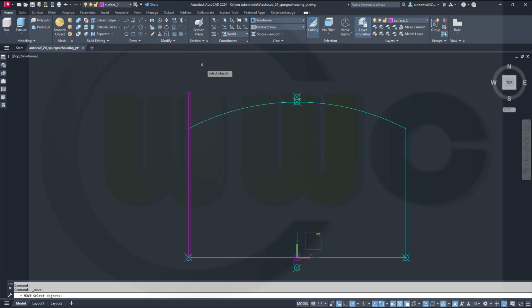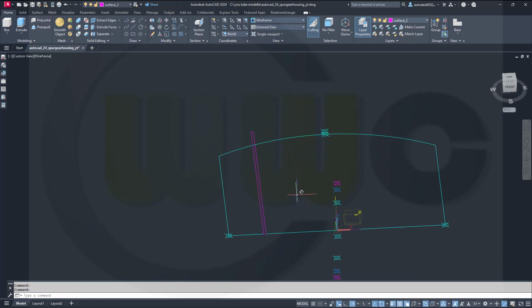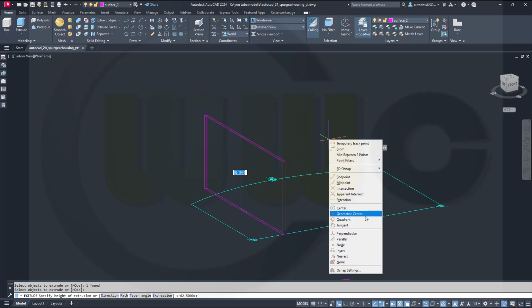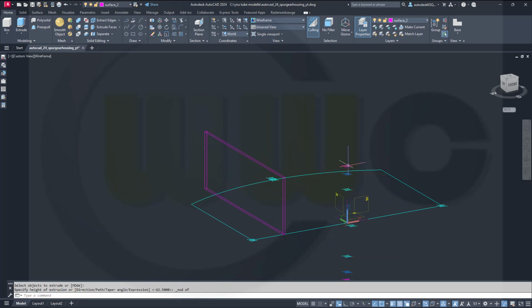So to the move, select that rectangle, right click. The base point could be anywhere, doesn't really matter. And move along that trace, and the distance should be 43.5 millimeter. Nice. Let's make an extrude. So go for extrude, select this one here, right click, enter, and can I go up to that node? Let's try. Go to that node, this one here, great.